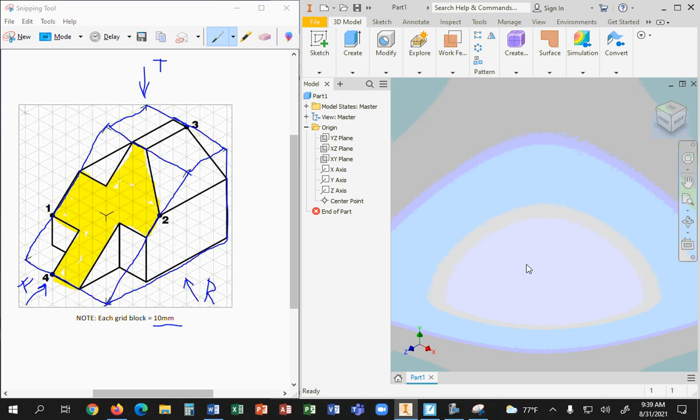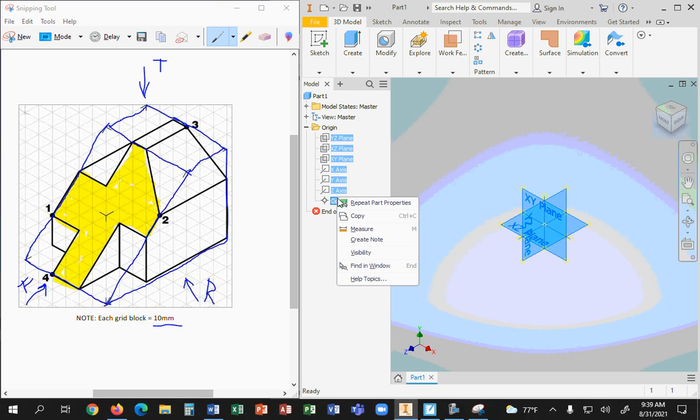Get it? So go back, pick the first item, hold your shift key, pick the last item, right mouse button while your mouse is over the items, and then you get a select set of options, including visibility. Just as a creature of habit, do that. There you go. Now all your planes are on, whether you click away or not.